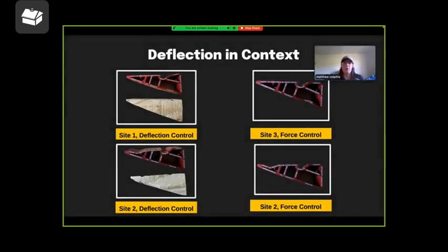So those numbers on the screen don't really mean a whole lot, but these are the pictures of what the tests actually do to the wedges. So as you can see, the wooden wedges only really dent. They don't have a lot of deformation, but you can still see that there's an impact. Whereas the aluminum wedges not only yield, but almost snap in the way that they break. So this is just a way of showing how that 4 millimeter deformation actually looks on a wedge.